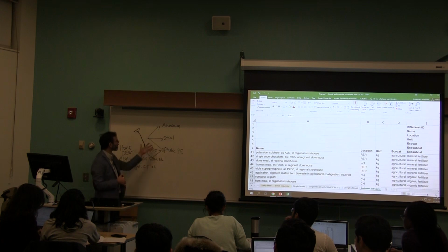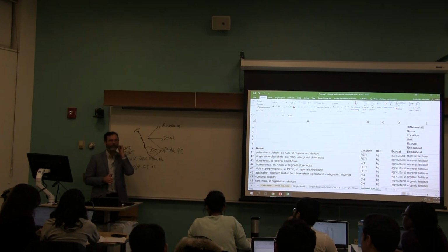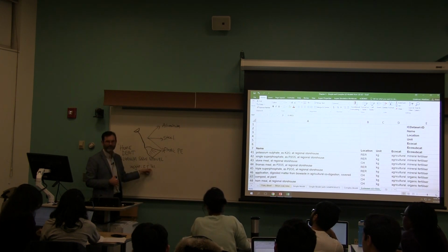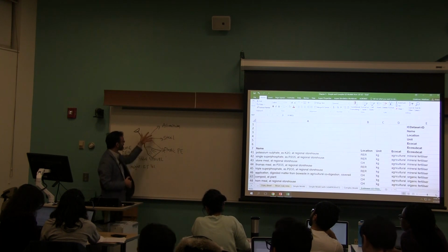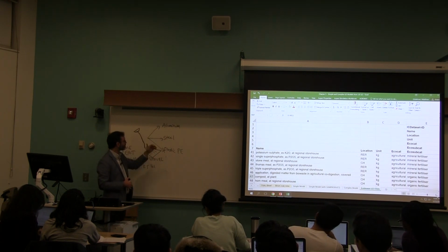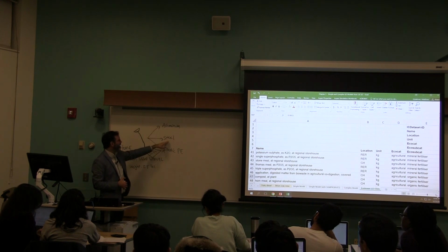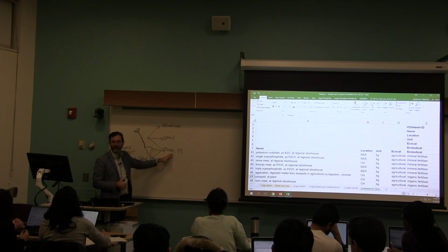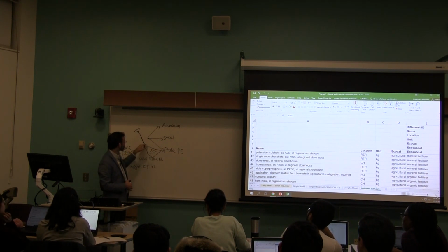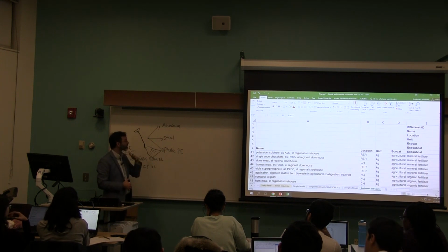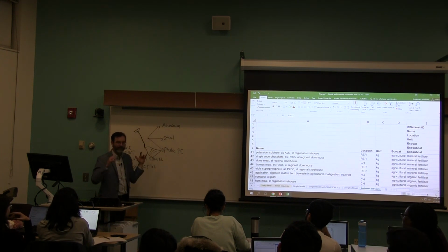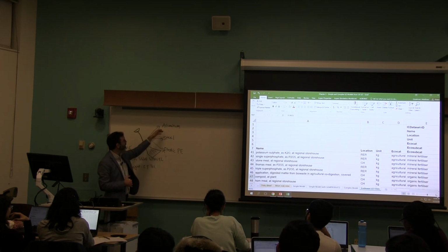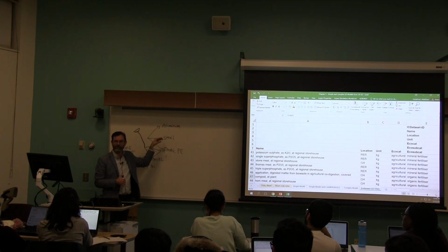Let's see. I found this aluminum snow shovel on the Home Depot website. It's 5.5 pounds, according to the website. I can see that it has an aluminum blade, steel hardware, the screws and rivets, and a high-density polyethylene handle. So what I'm going to do is try to figure out, based on my understanding and estimates, and manufacturer specifications if I can find them, the quantity of each of these.